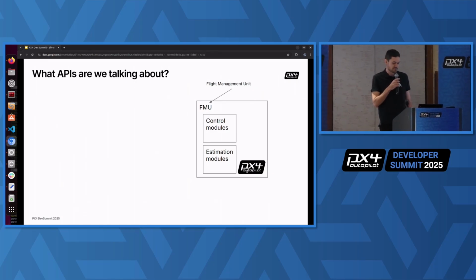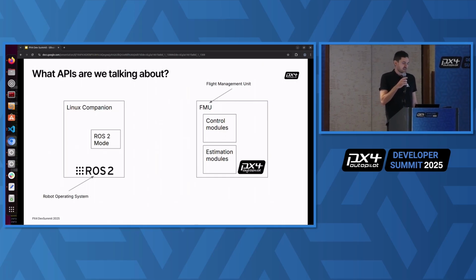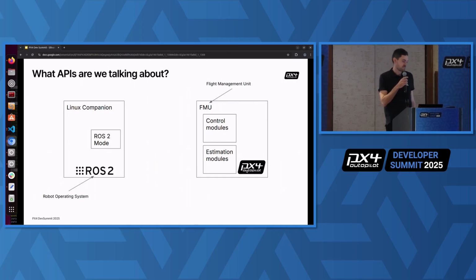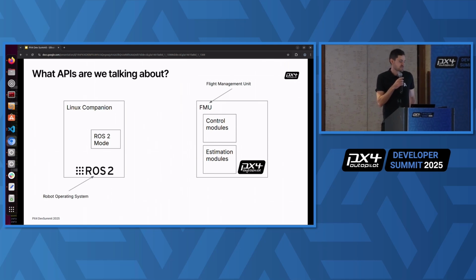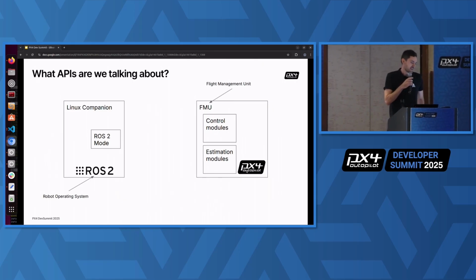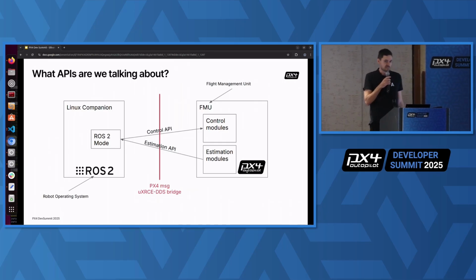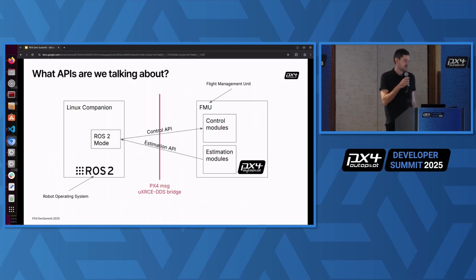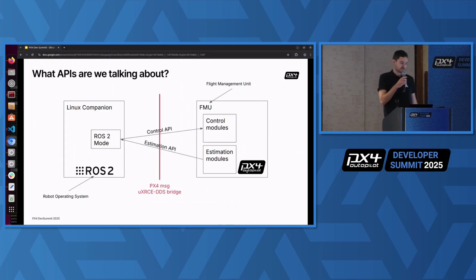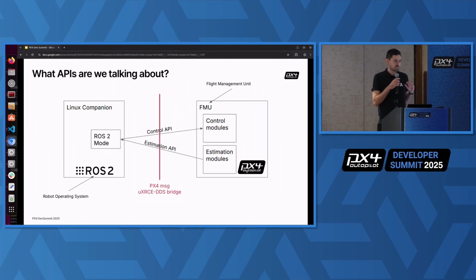It's really limited, right? And then that's why we have the option to extend abilities with the companion computer, usually running ROS2, having ROS nodes inside. Way more powerful computer, much more ability, a huge library online, and a very simple interface in between. Thanks to the DDS bridge that bridges between the two components, and us using the PX4 messages inside ROS natively as well. So we have a deep integration of PX4 inside ROS.